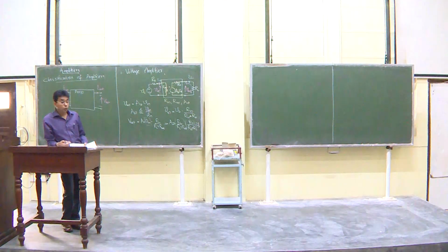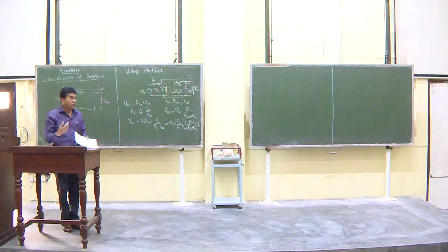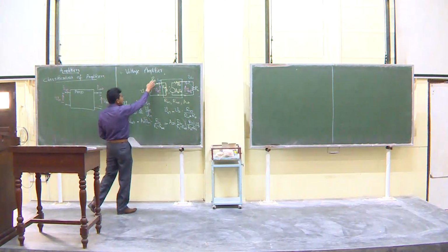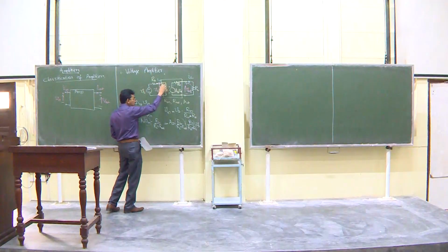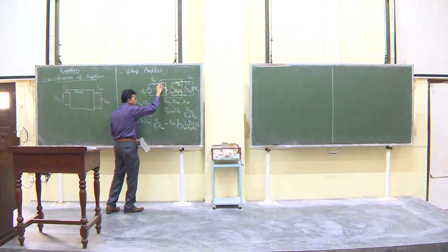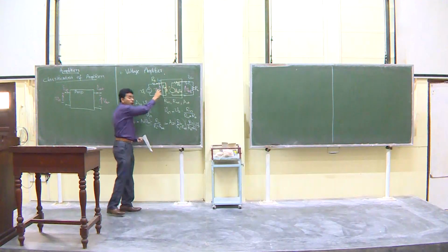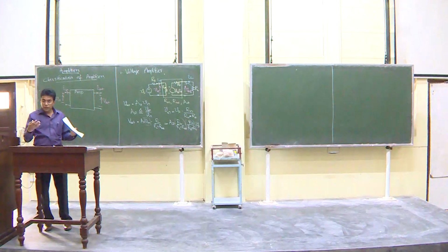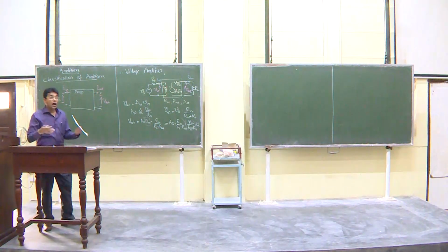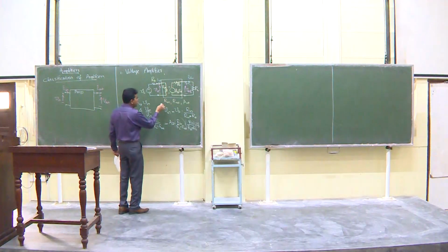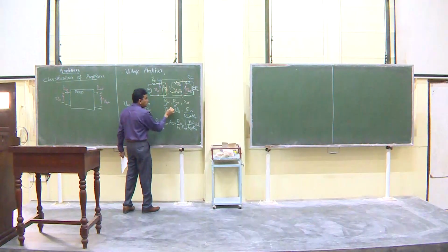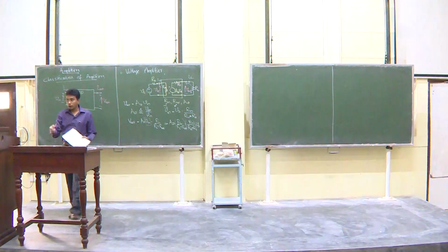It can be a very high output impedance source. Like if you are getting an ECG, it can be like 10 kilo ohms output impedance, you don't know. So, therefore, you don't have any access there. So, if you want as much of Vs appearing as V in, what would you like for R in? Should it be a small value or a large value? It's a large value, right? It should be as much as possible, ideally infinity. So, ideally R in should be close to infinity, R out 0, and AV whatever we like, the desired value.